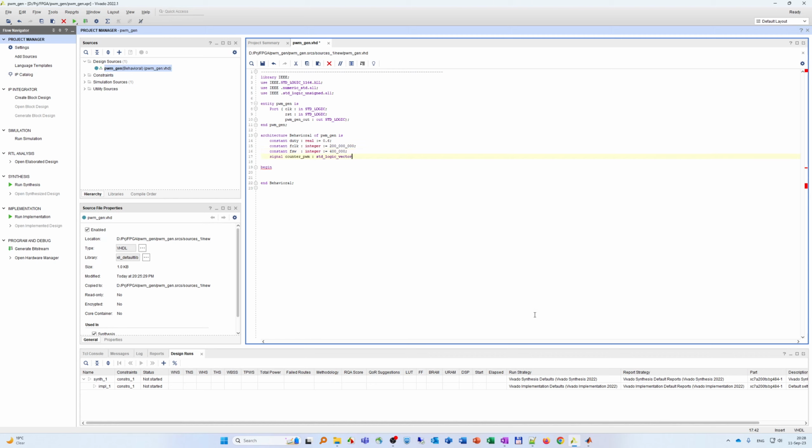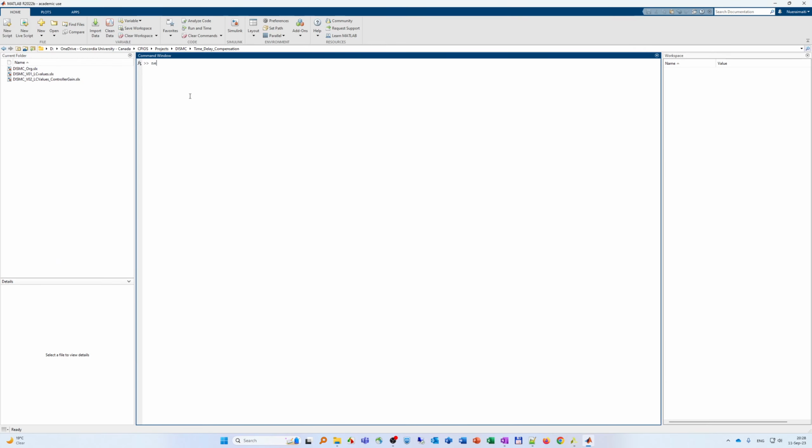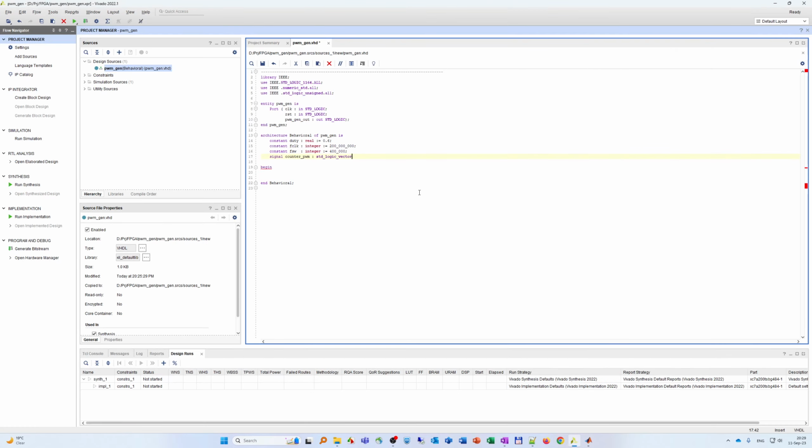So how many bits should our counter be? The next power of 2 above 500 is 2 to the 9th, so the smallest size should be 9 bits. It goes down to 0 because it starts from 0. So 9 bits is enough for the counter.